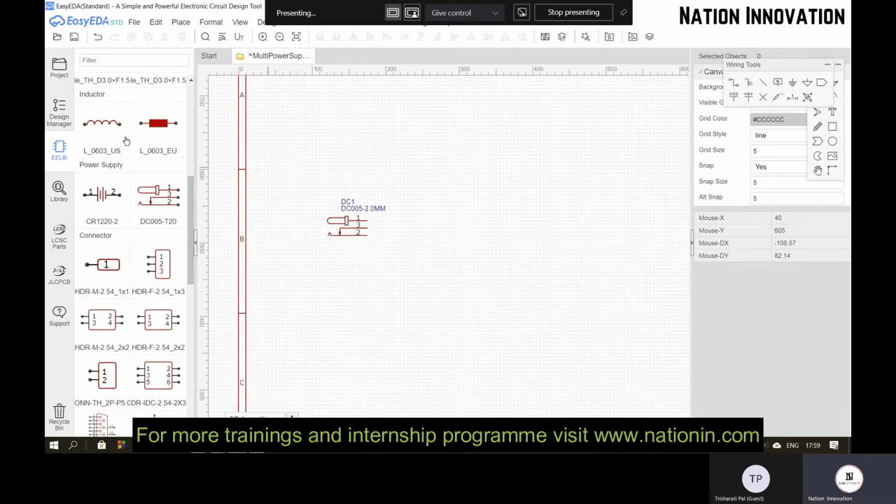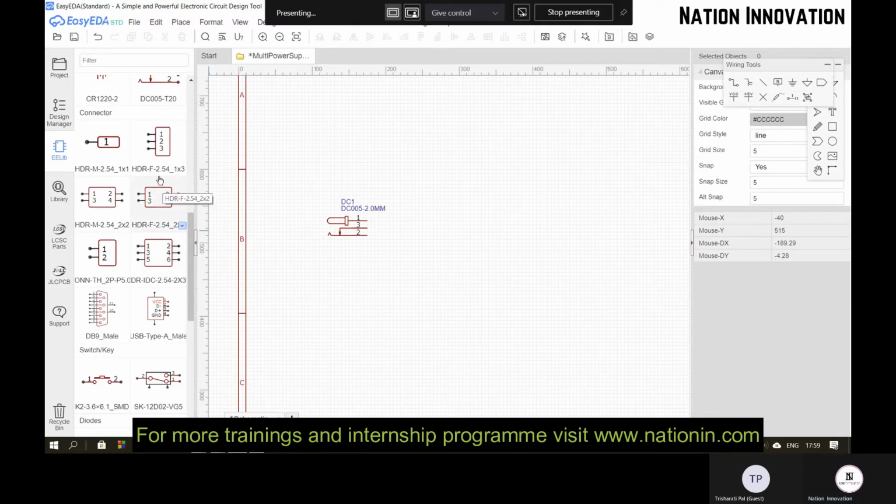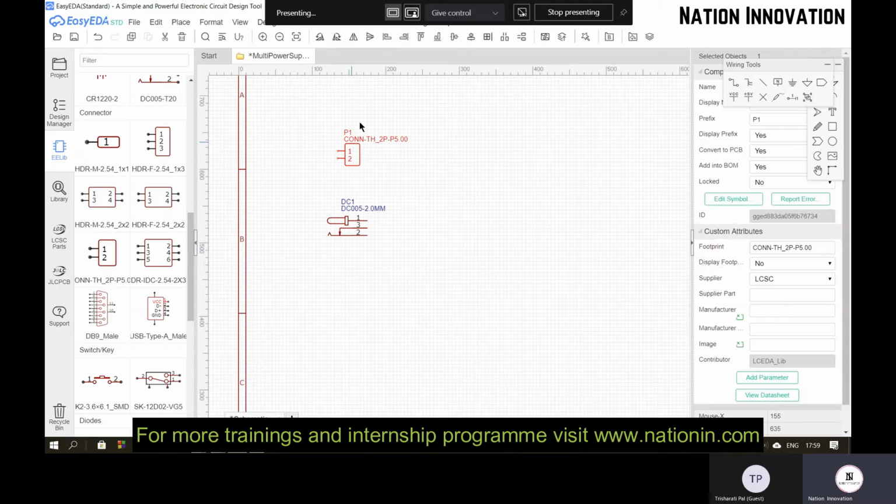And we need a 3-pin connector for giving the input supply. This is the header and this is the connector. This is the 2-pin connector and this is the through hole 2-pin connector. So select that and place it here. So flip this. You have an option called flip horizontally. So select that.